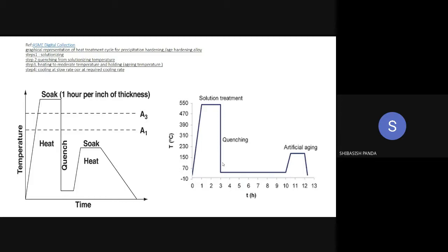That's why if you do slow cooling, the surface will become martensite, but the core will not become martensite. That's why we do fast cooling. Fast cooling gives you the maximum chance of forming martensite throughout the cross section. That's why there is a term called hardenability. Does anybody remember the hardenability term? I told you sometime in the IPM.